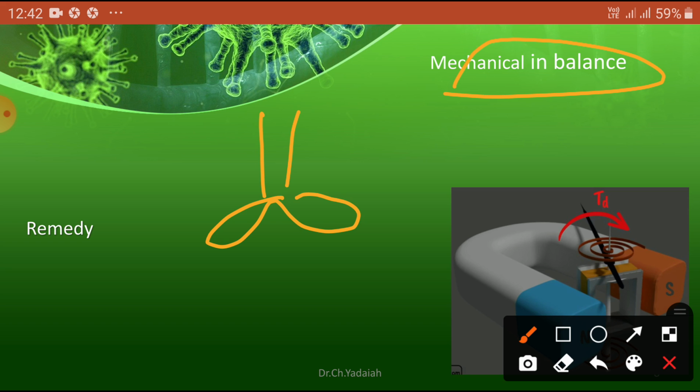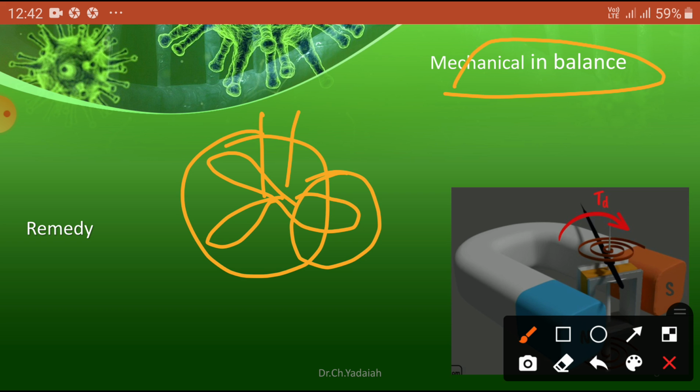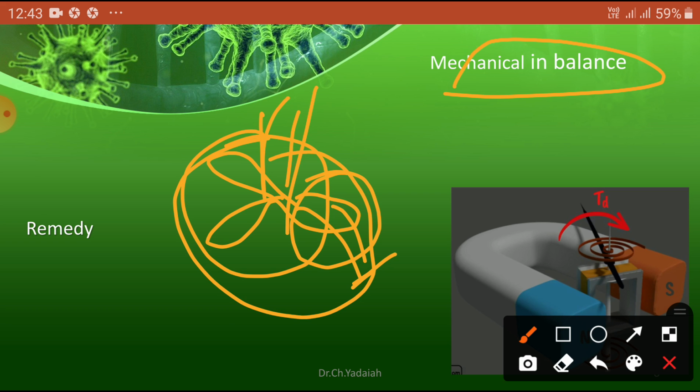If you remove one blade, the remaining two blades will still give air, but there may be mechanical vibrations, and unbalance takes place while it is rotating. Or if you twist or move one wing downwards, then automatically a vibration takes place and sound comes from the ceiling fan. That is the unbalance in mechanical.